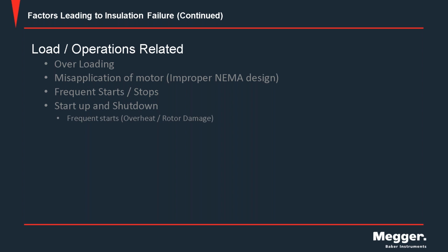Of course, frequent starts also have a high, almost up to 300% of the rated torque. So we're likely to damage our rotors if they're across the line starts, especially. And overheats, of course. Voltage spikes I mentioned. Inrush currents as high as 10. I think the highest I've seen is 13 times the full load rated amps for that short period of time.